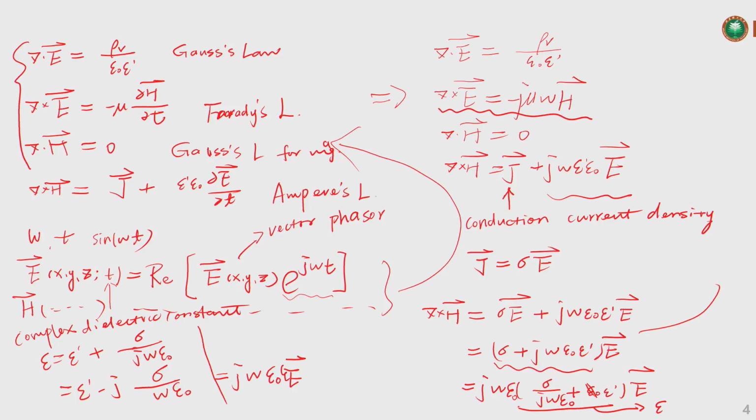So sometimes if you want to calculate the interaction for channel modeling, you can only find the refractive index of a kind of material, right? So when you use that for calculation, you're going to find a lot of discrepancy between your calculation and the measured data, because you lost the information about the imaginary part. So if we put this part into the theoretical model, we can get the propagation constant of the electric or magnetic field.